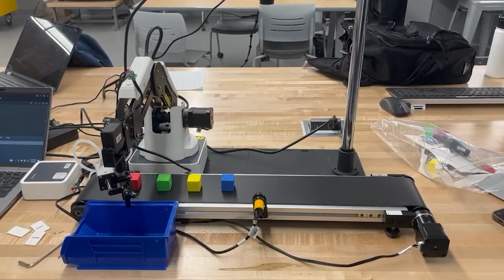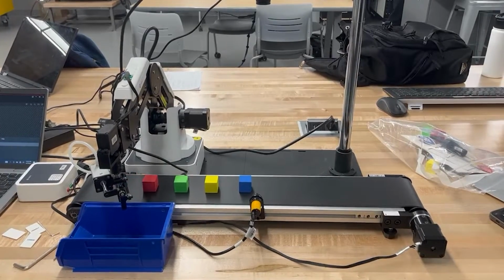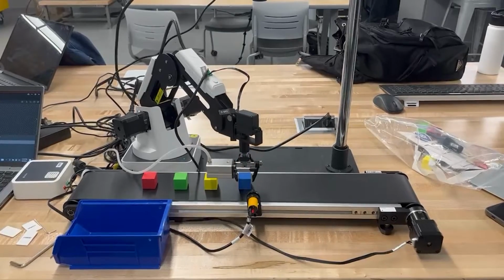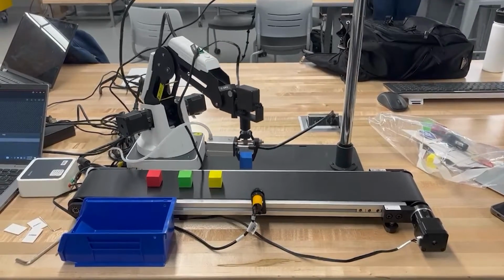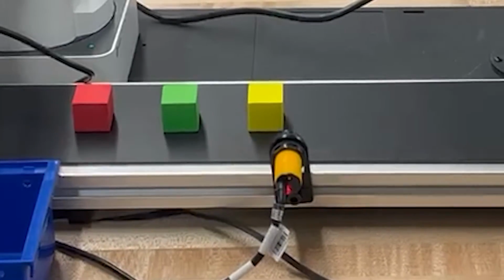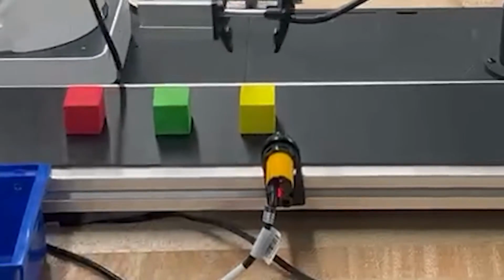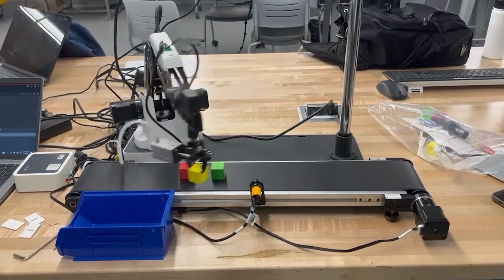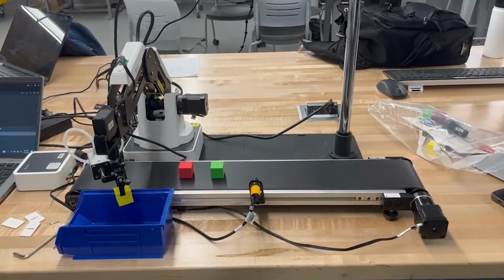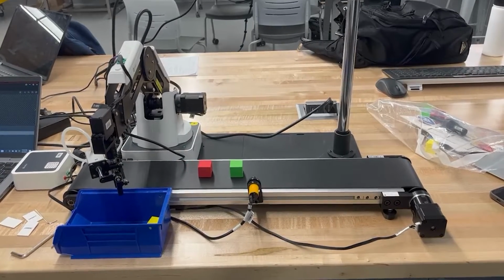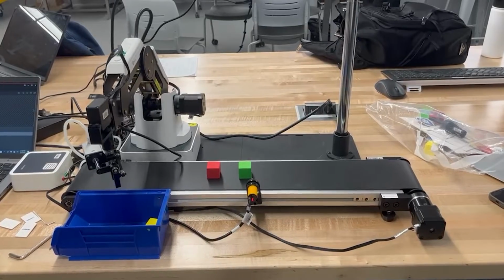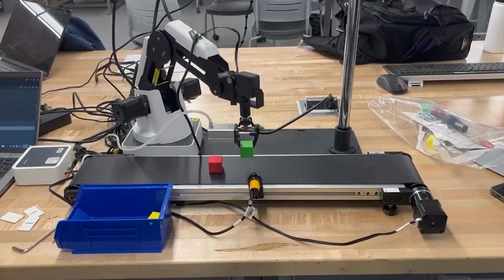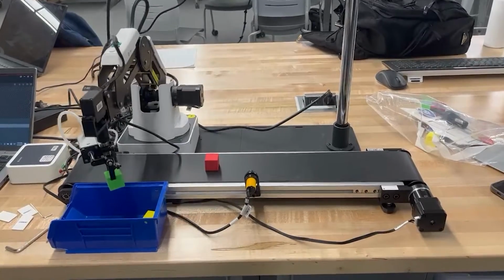The task, similar to real-world automated manufacturing procedures, utilized a conveyor belt. We would place a series of blocks on the conveyor belt, coding an IR sensor. The conveyor belt would move and stop once the block reaches the front of the IR sensor. Once the conveyor belt stopped, the team would use a suction cup end effector to pick up the block and move it from the conveyor belt. Once the block was removed, the conveyor belt would move to position the following block for removal. This process would be repeated until all the blocks were removed from the conveyor belt.